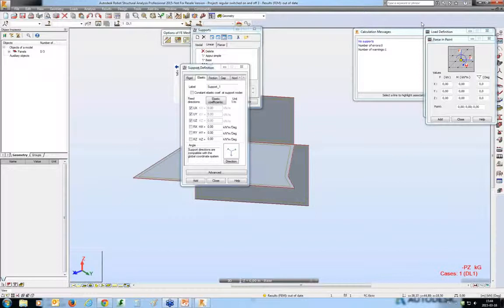Either I freeze the meshes which are correct and make local corrections to the planes, or just move the nodes. So from using the big guns to the tiny corrections, like moving two nodes and merging them. I don't know if this answers the question, but generally big changes first, followed by the tiny modifications.